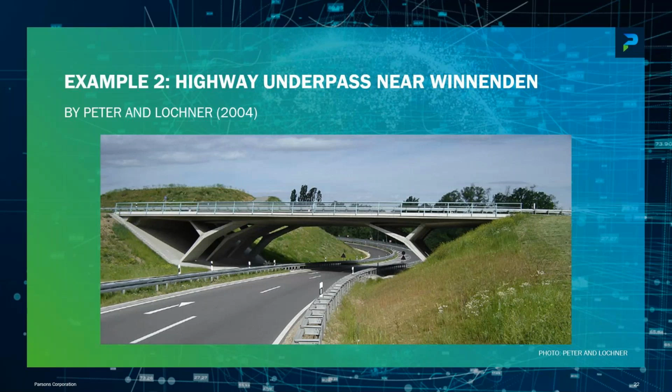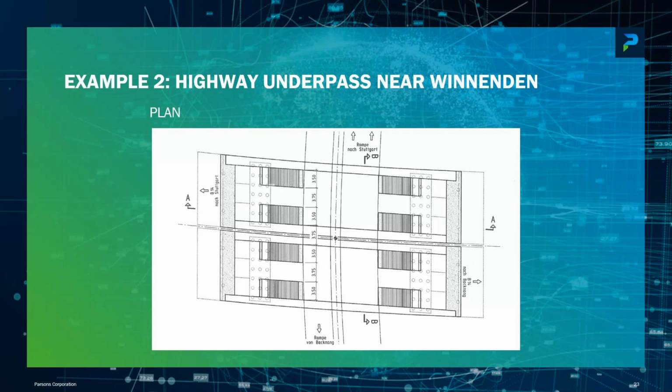But every situation is different and requires a tailored solution. And you see here, the highway is curved. The ramp is somewhat skewed to the highway axis. And then you will see later on that the highway has both the northbound and the southbound structure, and they have an elevation difference where they come close to each other. And that led to an idea to have two individual bridges, each bridge with two arches, and that again increases structural redundancy.